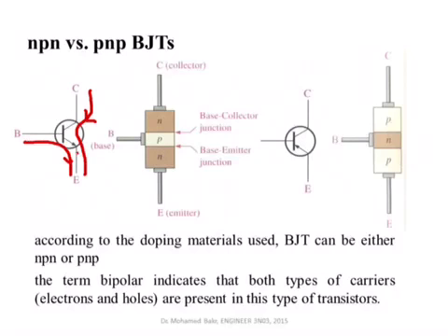This is a little bit different from what we learned with FETs, because in FETs we had no current flowing into the gate. Here for the base we have some current, not really a big current, it's a weak current, but there is some current flowing through the base, and the emitter current is equal to the collector current plus the base current. For a PNP transistor, the arrow shows the direction of flow of the current, and for the base, the current is flowing out.